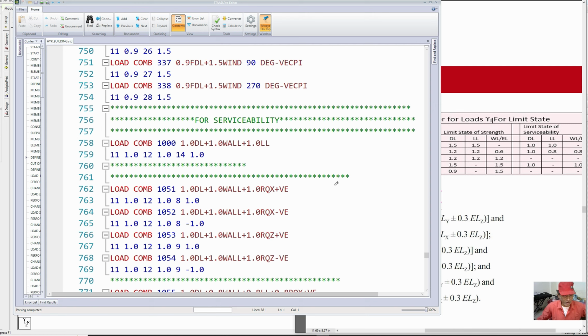On the other hand, because of the more stiffness, the lateral deflection will reduce. So the dynamic analysis with the VR frame is enough for estimation of lateral displacement and comparing it with the permissible deflection limit in the lateral direction.